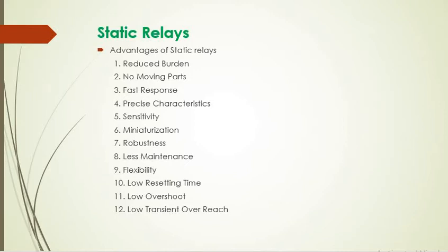Next advantage is low resetting time. Resetting time can be reduced using static circuitry, where fast automatic reclosing of circuit breakers is involved. The resetting time of a relay may be a critical parameter for obtaining selectivity. Next one is low overshoot.